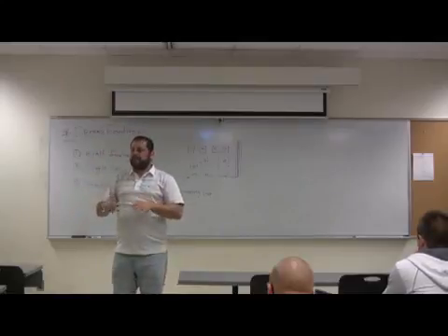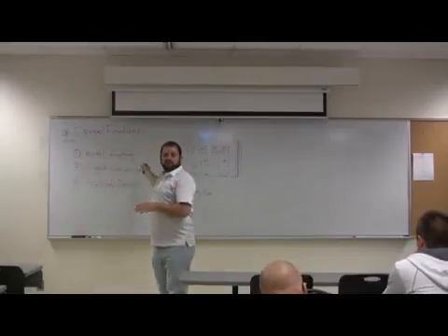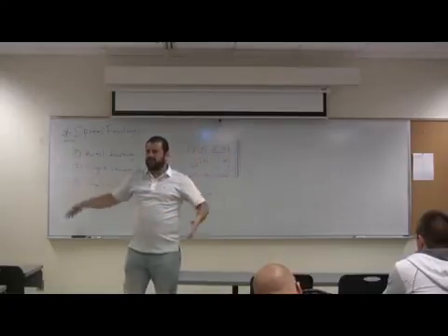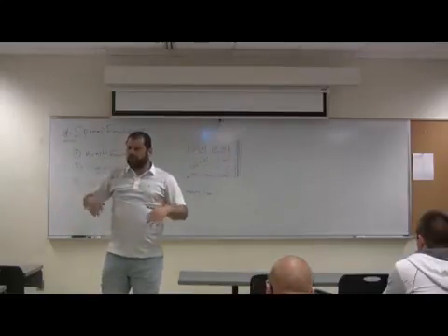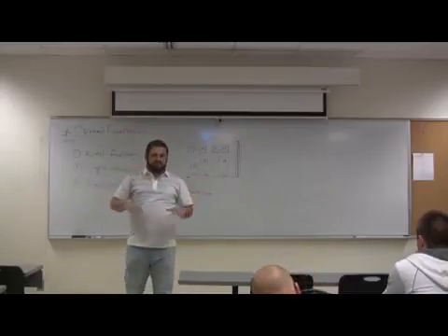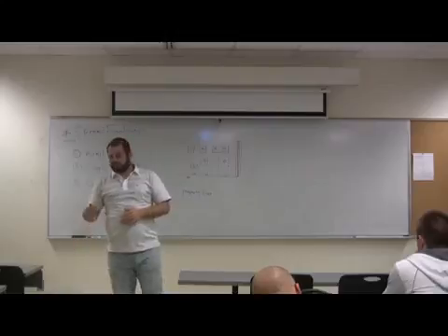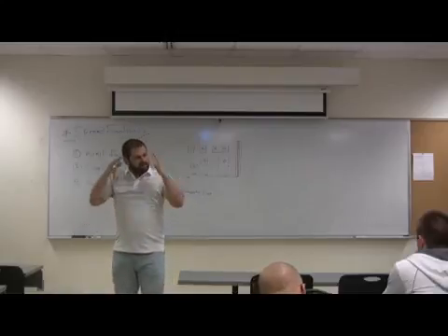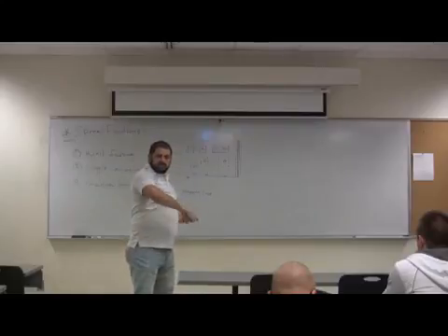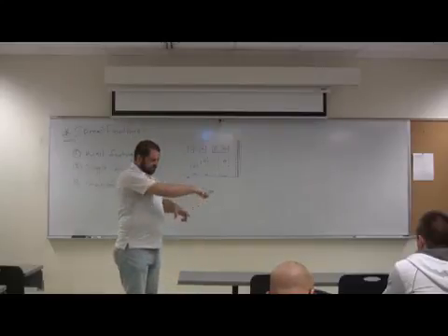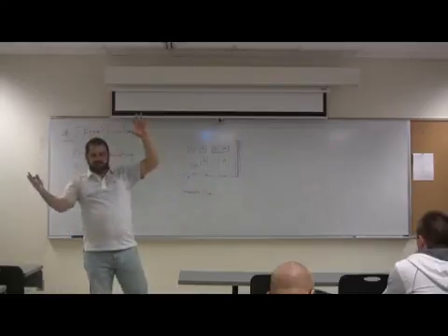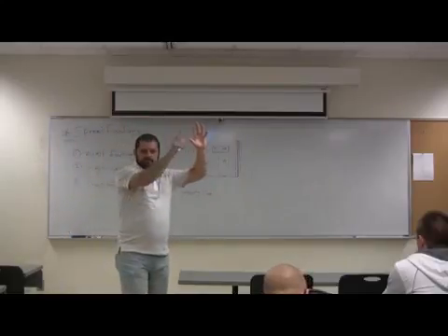When the sum of the areas of all the spread footings here exceeds 70% of the area of the building, it is more economical to go with one mat foundation for all of them. And that can be designed by finite element analysis, or by some approximation by taking strips. Whatever column lines you have, take one wide strip for that line, and you just flip the foundation, it becomes like a slab with columns.